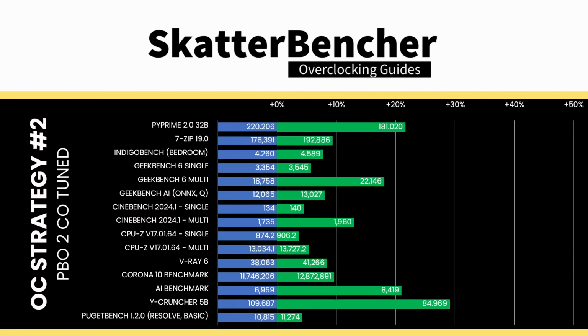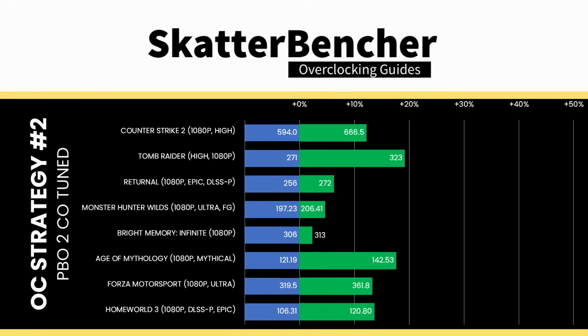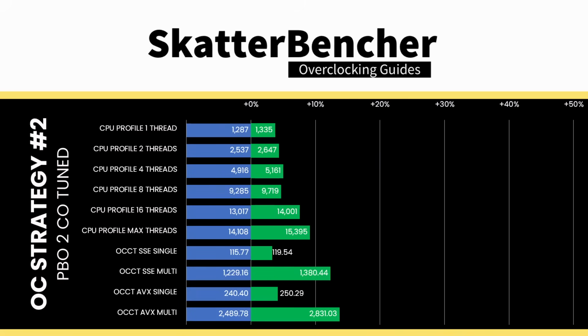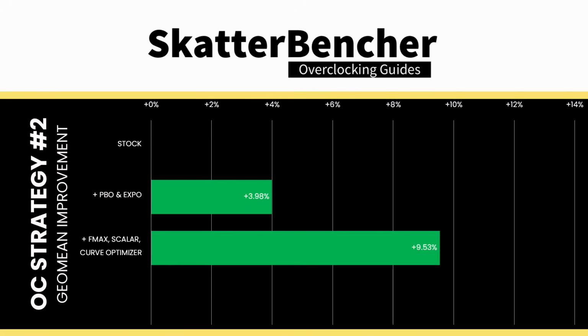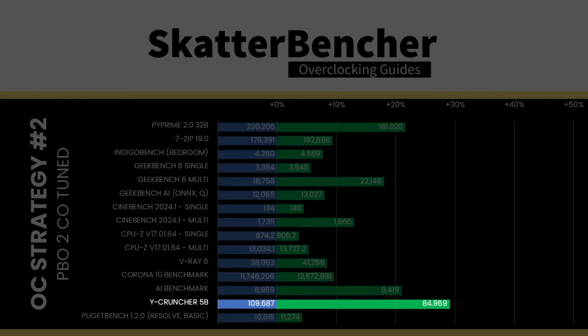We reran the benchmarks and checked the performance increase compared to the default operation. Undervolting with Curve Optimizer is a Ryzen overclocker's best friend and has been for a very long time. It provides this Ryzen 9 9900X with a nice frequency and performance bump. The geomean performance improves by 5.5 percentage points, and we get a maximum benchmark improvement of plus 29.09% in Y-Cruncher.